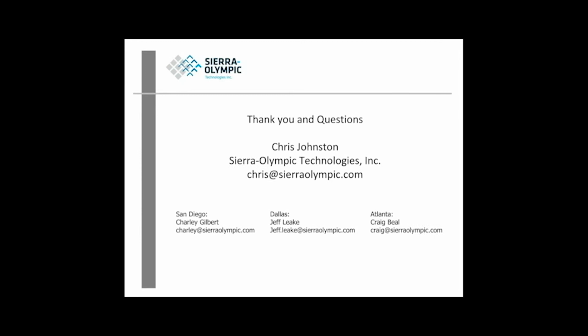Can you explain the difference between thermal imaging cameras and OGI cameras? So optical gas imaging, that's what OGI stands for. Optical gas imaging is a specialty midwave application that is only now being considered for airborne applications. OGI has a very narrow spectral bandpass, and the most common would be around the methane absorption line. That methane absorption line is at around the 3.2, 3.3 micron waveband.